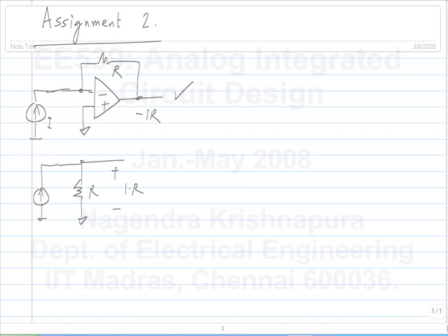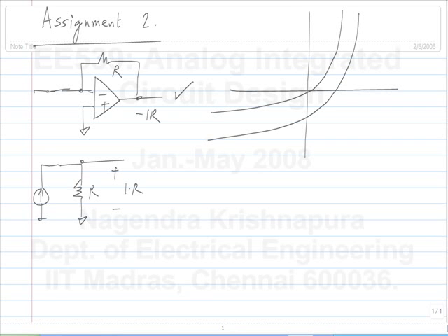photodiode amplifier, okay. So normally you have many signals appearing as voltage sources, but in a photodiode what happens is you have a reverse bias diode and then you shine light on it. Reverse bias diode, no current flows normally, but when you shine light, the current does flow, okay. So the characteristics of a diode, this is not the point of our discussion, but this is what happens. Characteristics of a diode are like this, okay. Now, when you reverse bias it, it moves, okay. So it acts like a source.